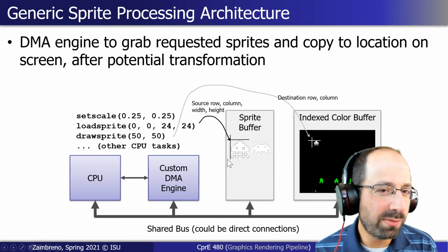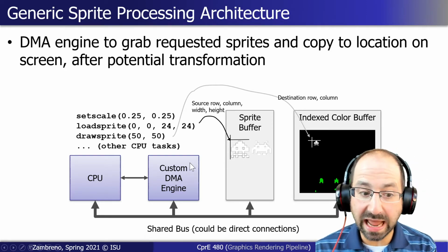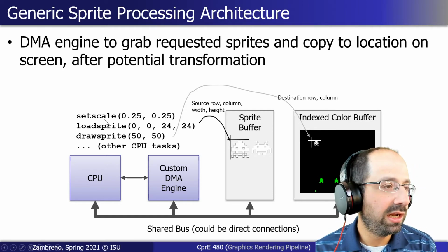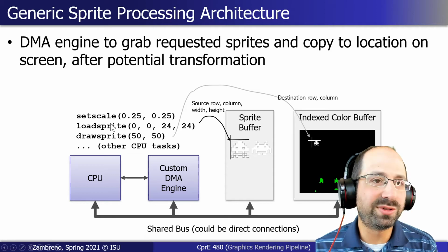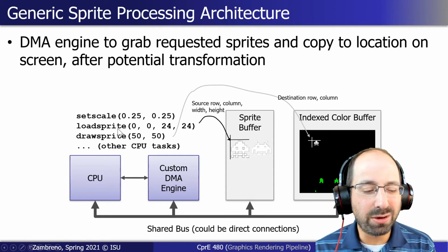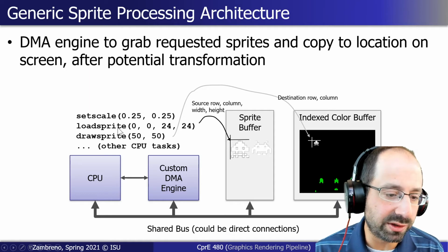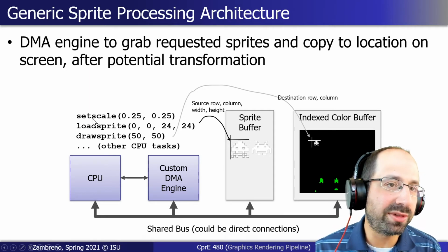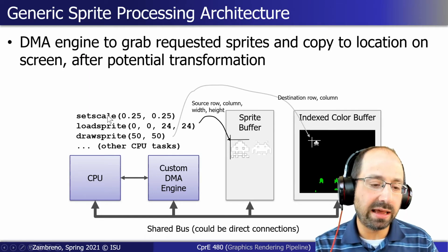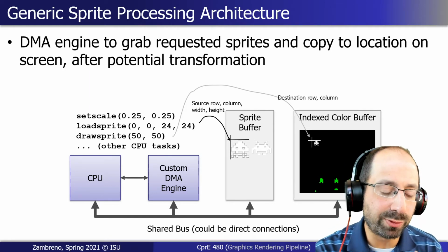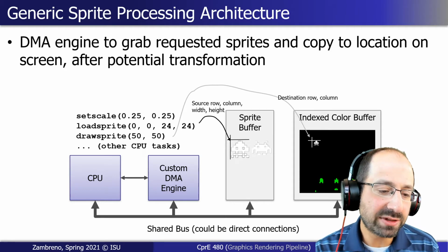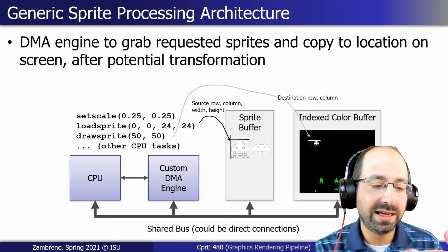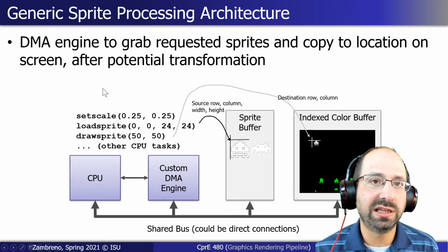So it's a little bit more than just a DMA engine like what we have in our SGP architecture now, because our DMA engine can do some of this, but certainly not all of this, right? We can do two-dimensional block transfers, or we can serialize it line by line, but we can't do things like scaling, or we can't apply blending operations directly in the DMA engine itself. But that was something that these type of architectures could generally assume, depending on what generation it was, more or less functionality associated with that.